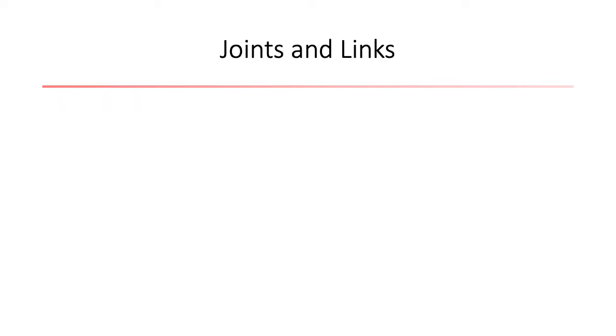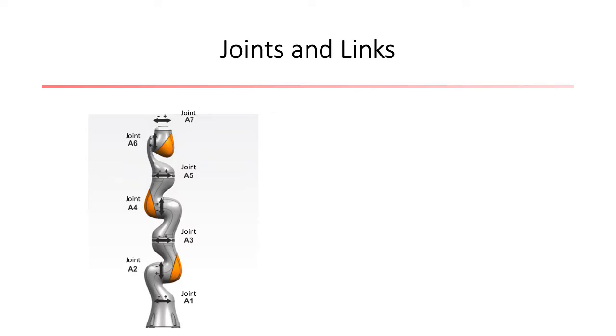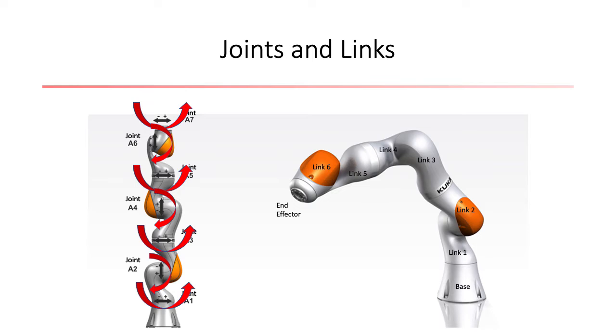Before going further, we will define what we mean by robot joint angles, or joints for short, and robot link positions, or links for short. By joints, we mean angles between articulated bodies measured relative to rest positions. In our work, all robot joints are simple revolute joints. By links, we mean the Cartesian coordinates of reference points on the robot's rigid bodies. In our study, there are 7 link positions corresponding to the center of mass of the robot rigid bodies beyond the base, as well as 3 link positions placed at the endpoints and center of the stick used for interception.